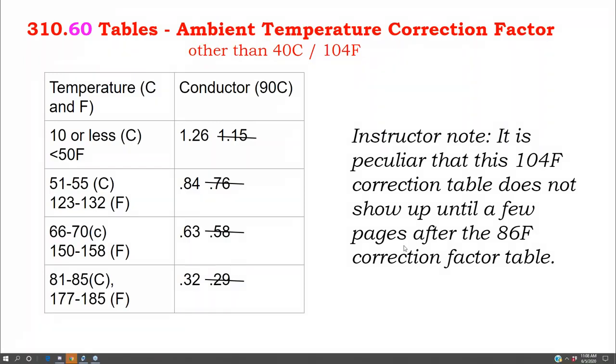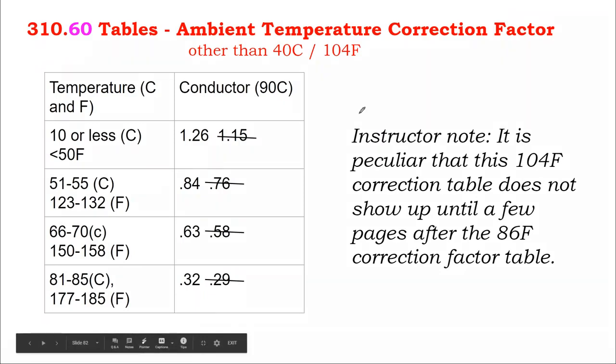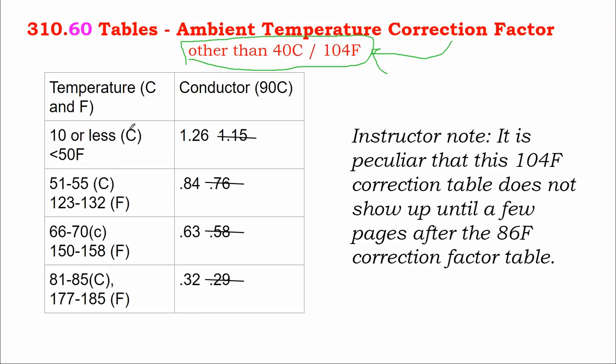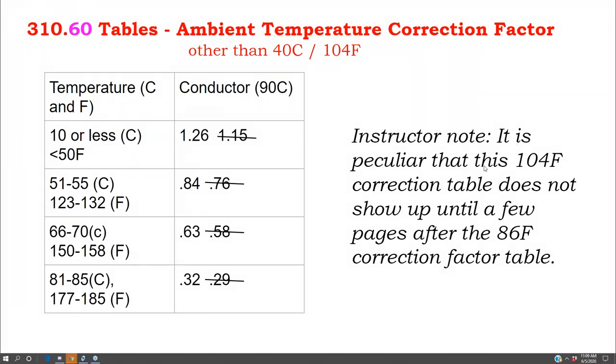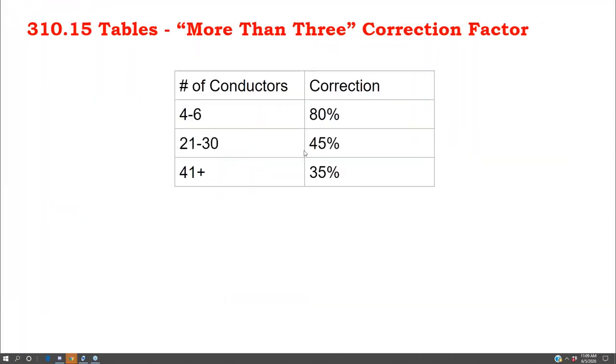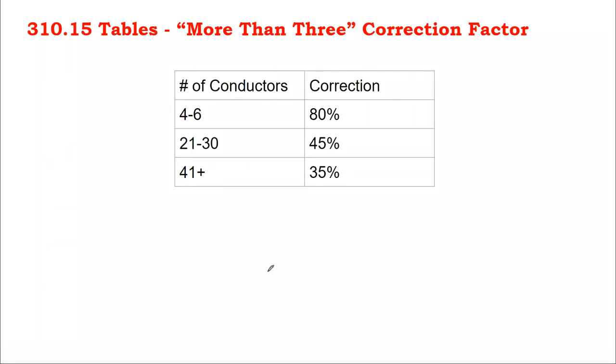And that, because a conductor in free air has much better temperature dissipation than inside of conduit, will have a different ampacity rating than inside of conduit. So you have to read the chart title headings and make sure that the modifier in the title heading makes sense for your case. So in addition to the difference between a conductor being inside of conduit versus in free air, that would be one difference in operating heat.